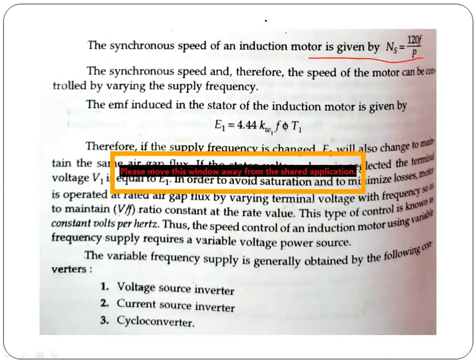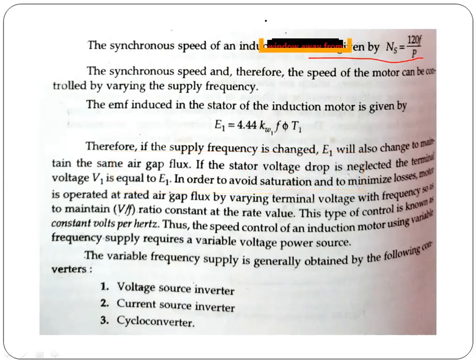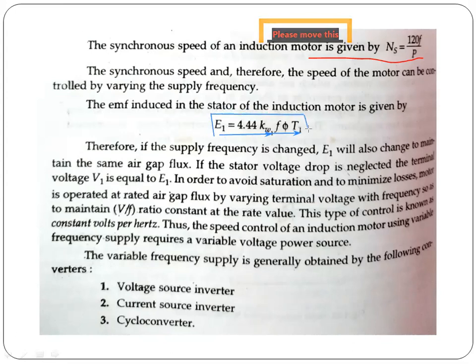The EMF induced in the stator of the induction motor is given by E1 equals 4.44 k w f phi m T1.